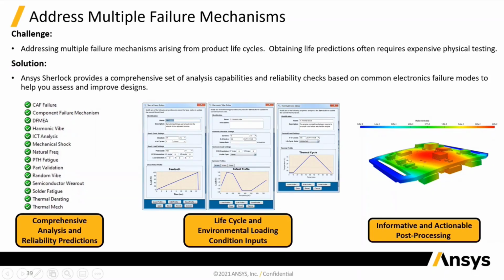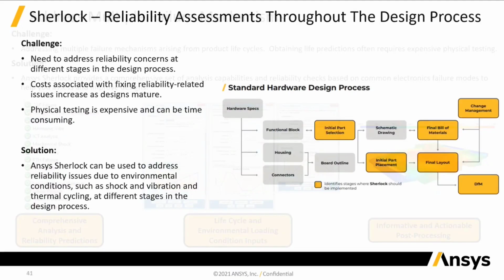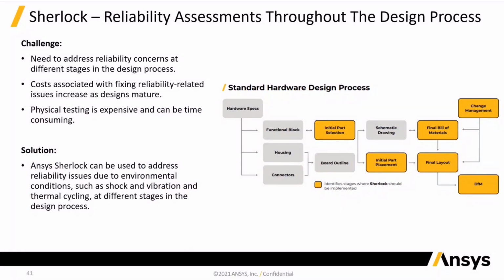And again, Sherlock not only allows you to understand the impact of this loading on the lifetime of the components through the Weibull curves and the tables, but you can also see the hotspots as shown by this sort of heat map type diagram. So you might be looking at the thermal response, or you might be looking at the vibration response on the printed circuit board, and you can see the areas where this might have the most impact. And this is valuable information that you can then take back into the design itself and understand how to fix this.